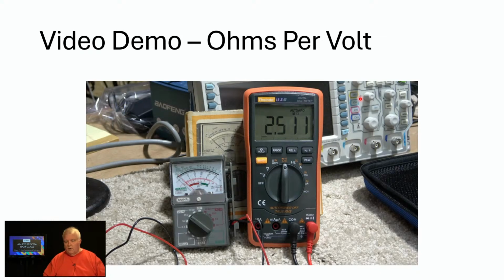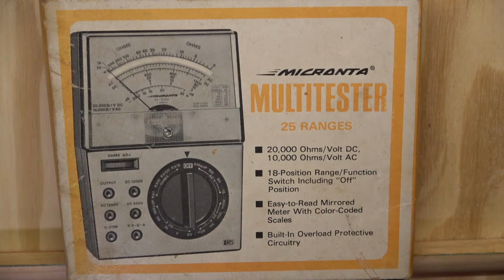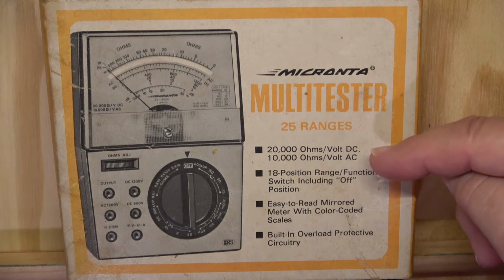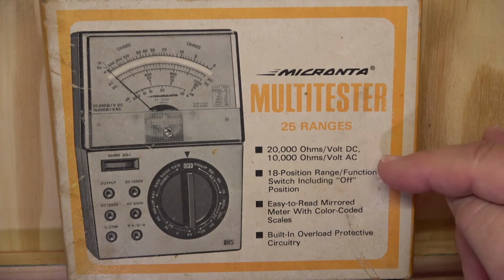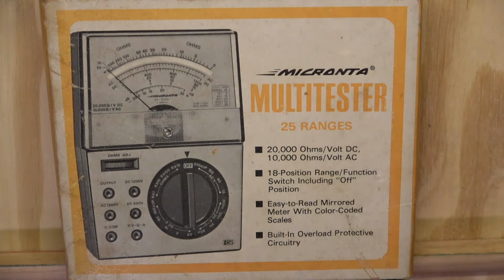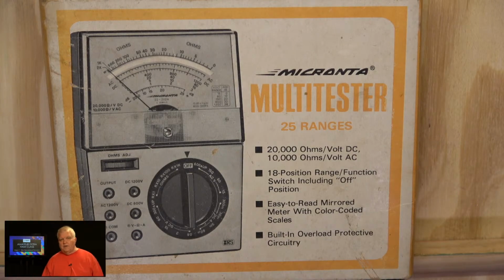So that's important to know, and in fact, if you got service literature from Howard Sams or somebody like that back in the day, they would have voltages written on the schematic, and it would tell you what meter they used in order to make that measurement. And if we go over to the calculator cam, here's a Radio Shack multimeter, and notice that it's rated at 20,000 ohms per volt on DC, and 10,000 ohms per volt on AC. So just keep in mind that this is a common specification for analog and digital multimeters.